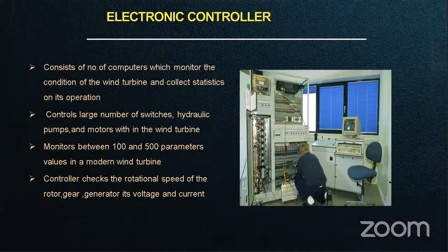The control system can get information from the various instruments which are fixed on the turbine. For example, the gearbox oil temperature should not cross more than 80 degrees. If it goes more than 80 degrees, it will keep checking, and give alarms and logs. If it goes beyond a certain limit, it automatically gives the information to the controller: now I have crossed, the temperature is 85 degrees.